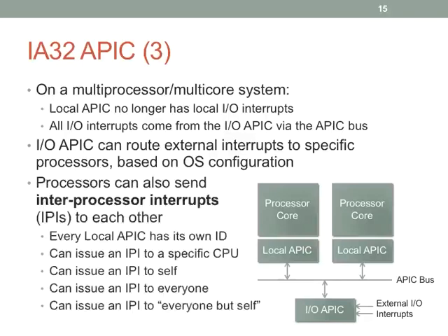Processors can also use this APIC bus to communicate with each other. So every local APIC has an ID. You can actually use, I can't remember if it's a CPU ID instruction or CPU info instruction, or if there's somewhere else that you get this information from. It's been, I think, a year or two since I looked at this. But you can retrieve the APIC IDs in software, and then you can use that to cause an interrupt on a specific core.